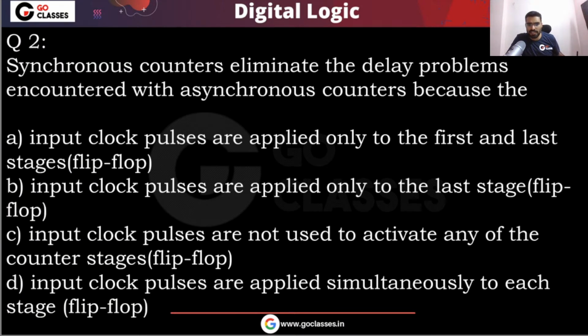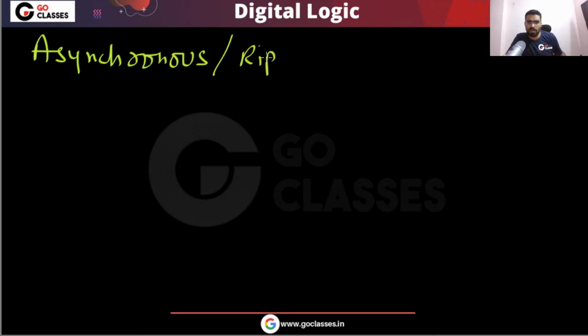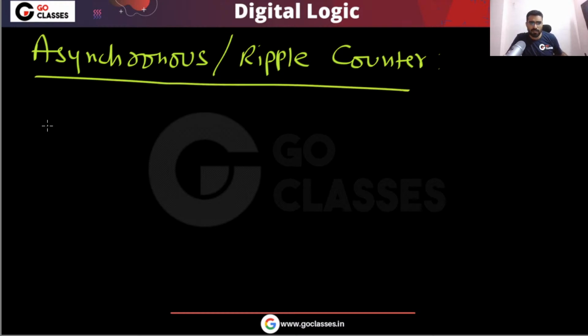You know what happens in an asynchronous counter? This we have already seen. What is the problem with an asynchronous or ripple counter? Do you remember? What are the major problems with an asynchronous or ripple counter? The first major problem is transient states. Okay, this is the first problem. You get transient states.